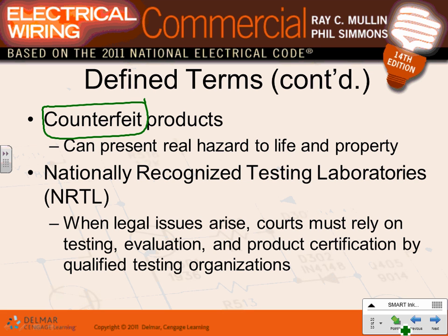I can give you a good example. I work for C Electric, and we had a clinic here in Minneapolis. When you do healthcare facilities, clinics being one of them, you have to use two grounds, right? So you go buy cable, and it says healthcare facilities on it, but it was made in Canada, and it doesn't meet the UL listing here. Our electrician bought it because it's an open market. They installed it, and the inspector refused to approve it. Even though it has two grounds, it's not listed to be used in the U.S. in a healthcare facility. So it's not counterfeit, but it's not listed. It creates a lot of issues.